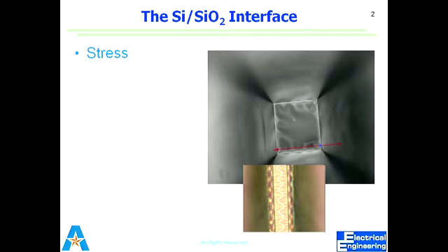There are two types of stresses actually. One we call the residual stress. In the oxide layer, the residual stress is due to the difference in the thermal coefficient of expansion. We grow oxide at very high temperature, maybe 1000 or 1100 or even more.